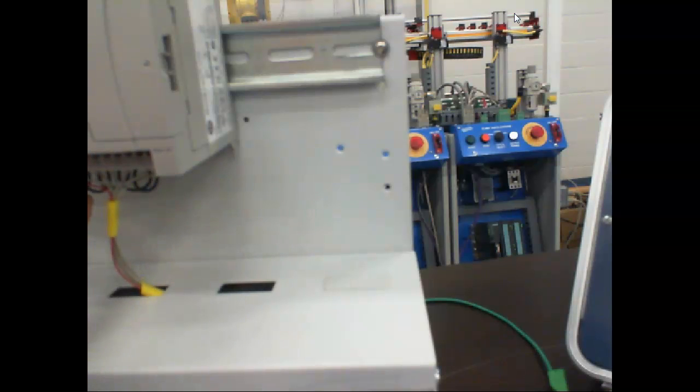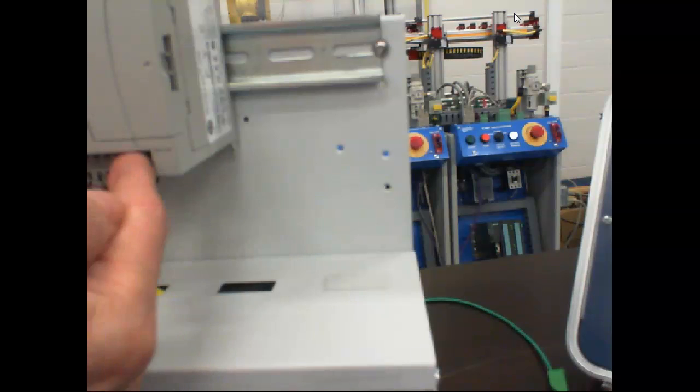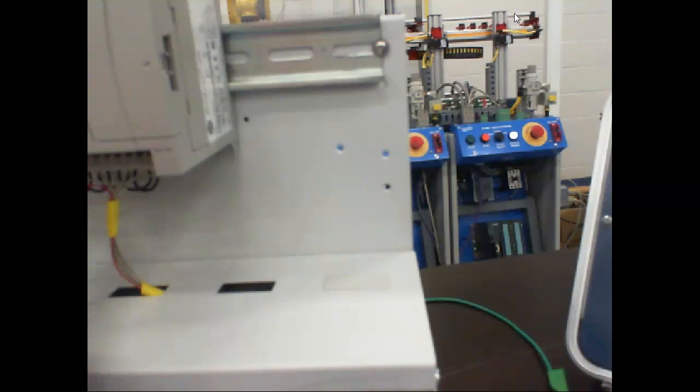Even though it's a black wire, that's all I had at the time. And so I ran it to each common, but I could take this one off and run 120 volts AC. So on this PLC, one output could be 24 volts AC in an HVAC system. The other output could be 24 volts DC. The next output could be 5 volts DC. The next output beside that could be 120 volts AC.